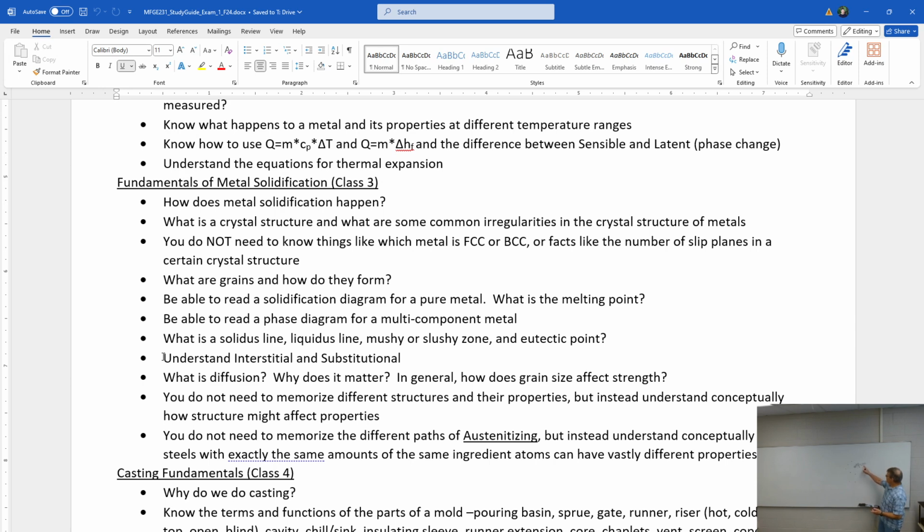Yeah, so in this structure, is the structure perfect? No, not at all. There are all kinds of things that are imperfect about the structure. It has impurities in it. It has dislocations, which are just gaps where the thing didn't grow quite in the right order, and so it may have rows that just dead end, or it may just have a missing component.